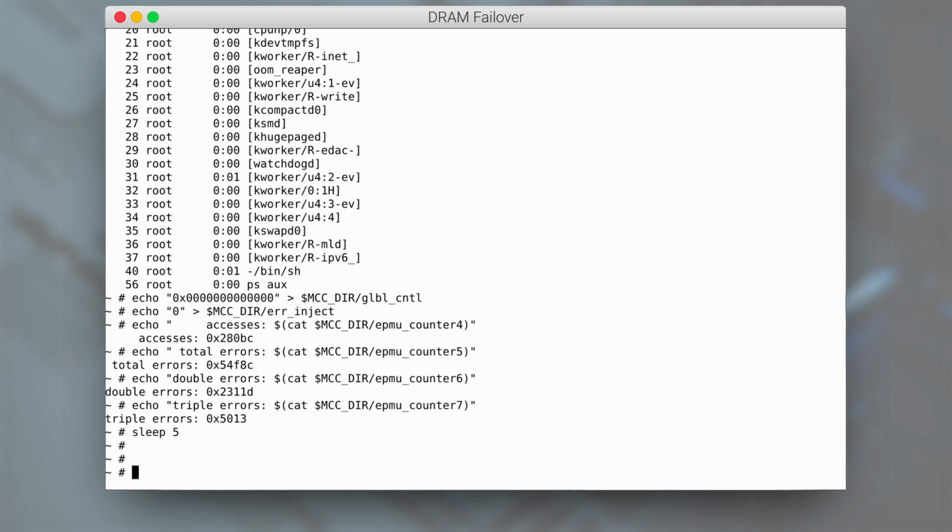This is the limit of the device's ECC correction capabilities in this mode, which is what is most commonly used. Any errors beyond this point become a data loss. We can recover from two hard errors, but any further errors would cause an unrecoverable data error. There's simply no more ECC to get the data back.